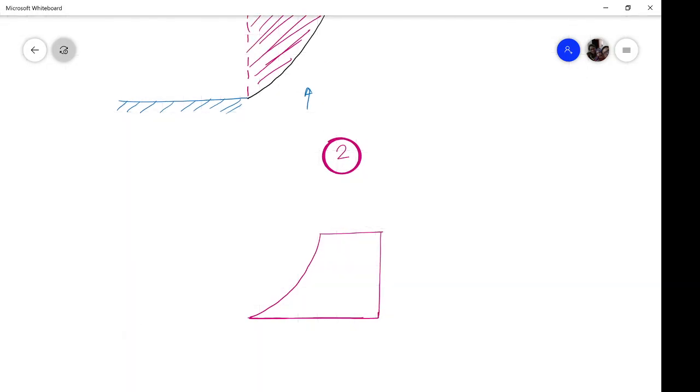Okay, then what is given is that at this point you have pressure P. If this fluid is of density rho, and at this point the pressure is P, then if you remove the lid, and the same pressure P has to prevail, then this rho has to be there up to some height. So what is that imaginary height? That will be equivalent to this pressure. So this P can be written as rho g H equivalent. So that H equivalent will be P by rho g.